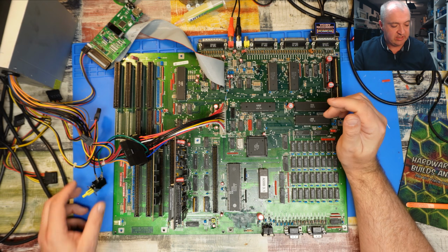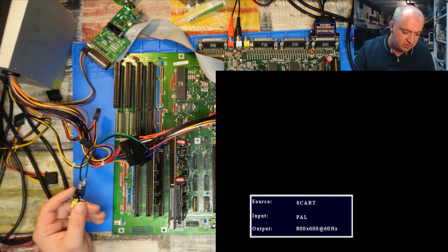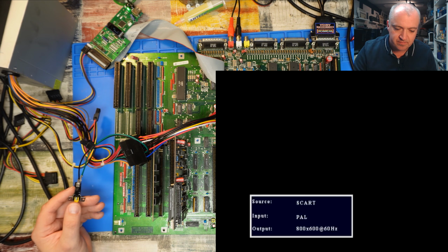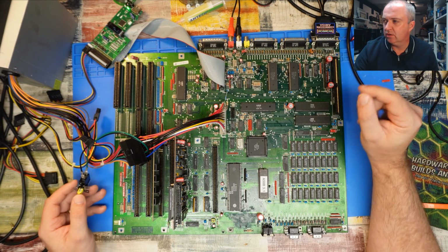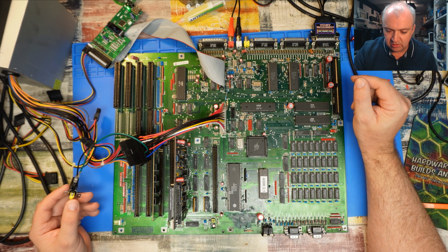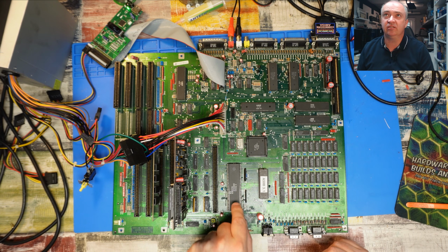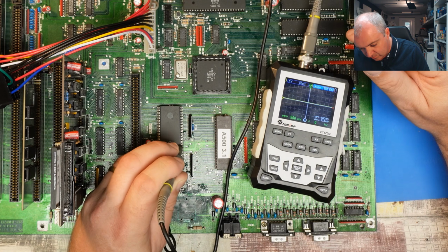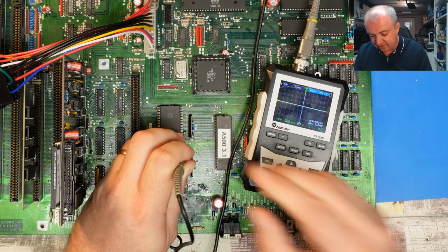And let's give it another test. Does it still power up? No, it doesn't. We've broken it. Maybe that isn't an equivalent part, although I thought it was. But seemingly not. I'll bet you that CPU is being held in reset. Yeah, active low signal. It's stuck in reset.